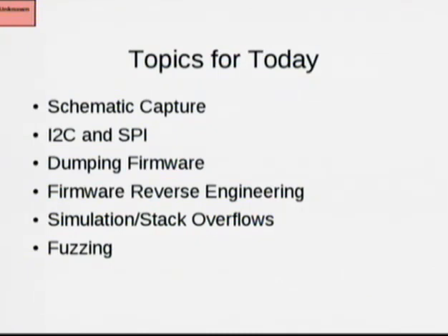We'll discuss how to extract and dump firmware. So having captured this device, you want a copy of its programming. Unlike in the PC world where you can just purchase or download whatever software you wish to attack, in this space you very often have to extract it from a functioning device which has had, say, a fuse blown to protect the device from you extracting its firmware.